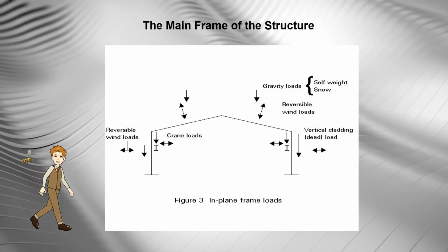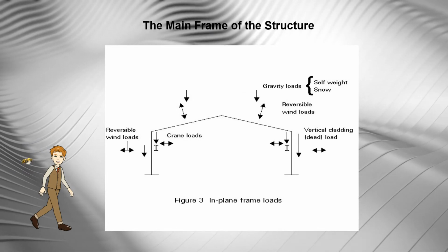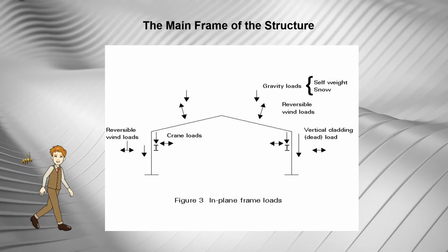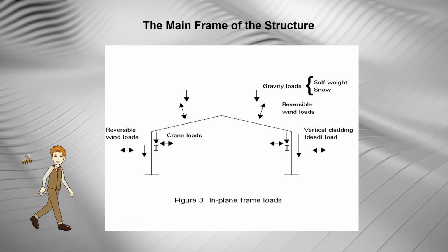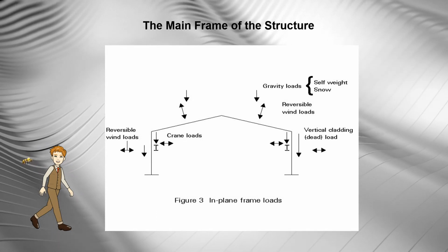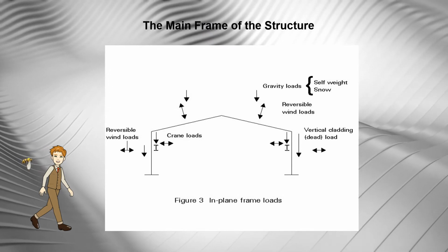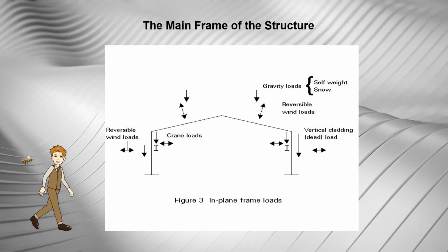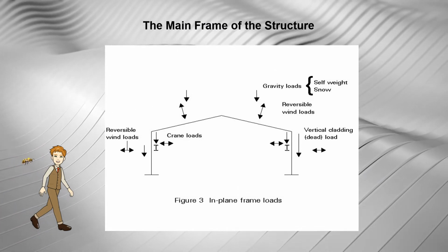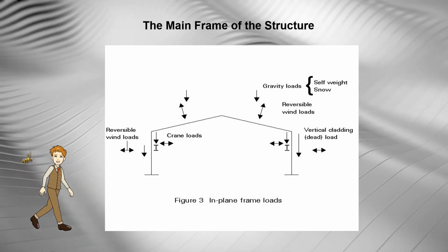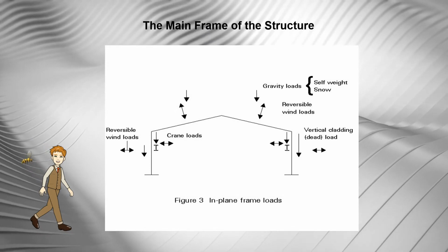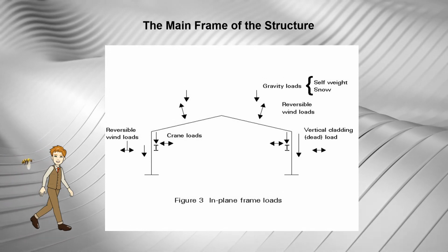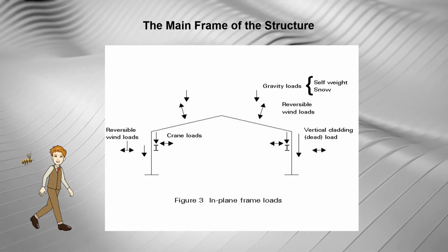When the length of the structure is not too great, say 50 to 100 meters depending on temperature range, it is normal practice not to consider the effects produced by changes of temperature. Wind can of course cause pressure, suction and drag loads on the cladding. Figure 3 illustrates the various components of load to consider in the design.